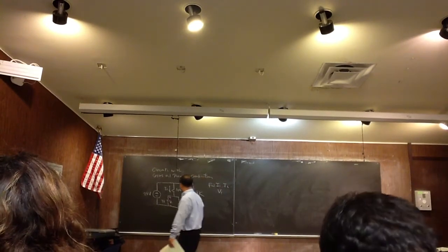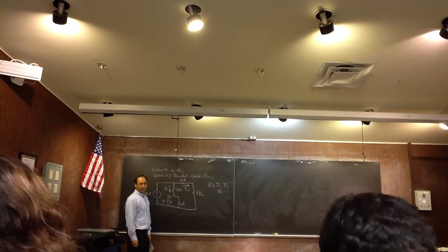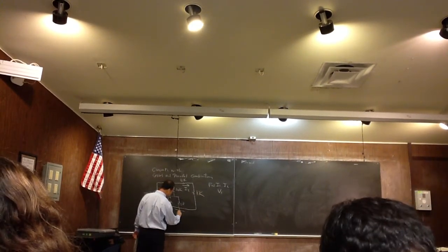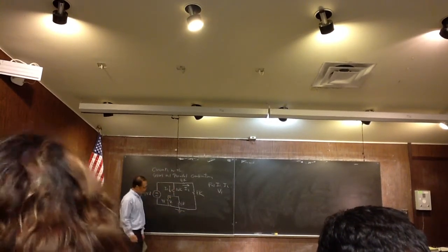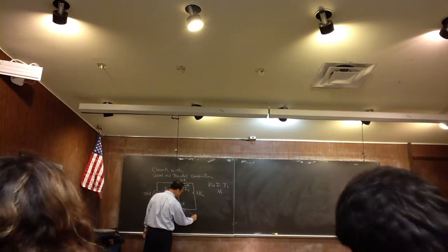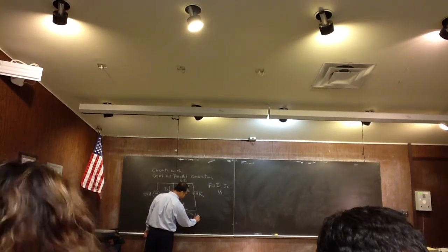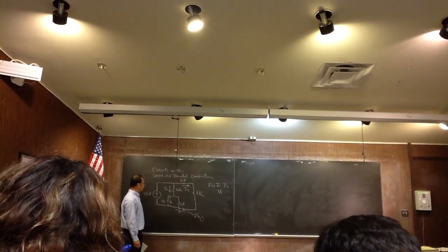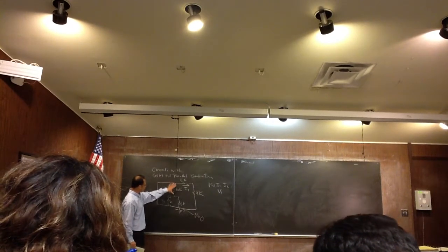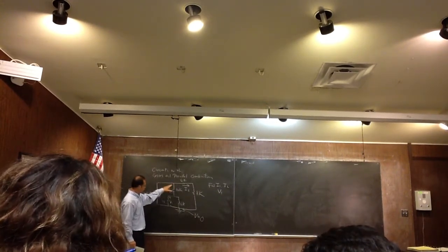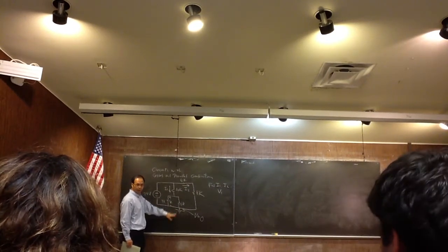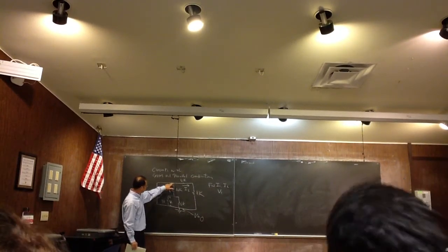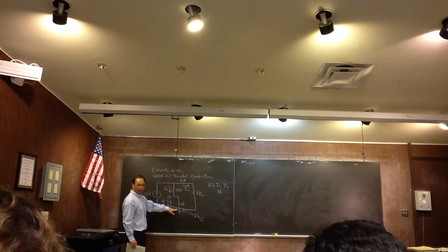Normally, when we have a node on the bottom of the circuit, that node is normally called the grounding node, ground. Okay, so I will use this symbol as the ground. When we have a ground, that means the potential here is zero, right? So voltage is equal to 0. And then all the voltages in the circuit will be referenced to that ground. For example, if I'm looking for the voltage at this node, then that will be the voltage at this node to the ground.